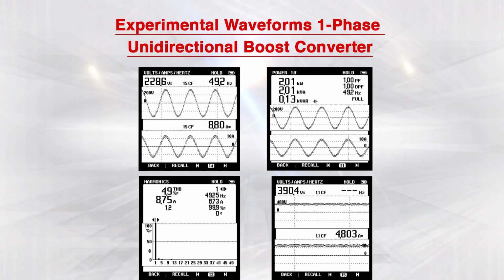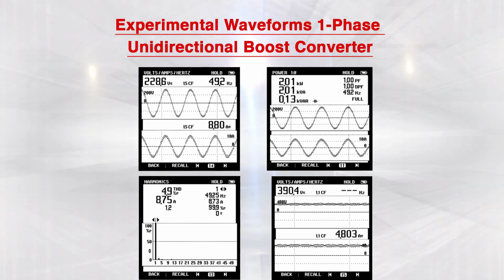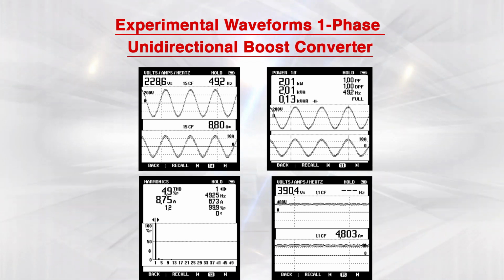Here you can see in the first figure the voltage and current are both in phase and perfectly sinusoidal, and the total harmonic distortion at the input current. Whenever I talk about input current, it means we are talking about grid current. So, at the input of the diode rectifier, the total harmonic distortion is 4.9, which meets the standard which we discussed in the introduction part.